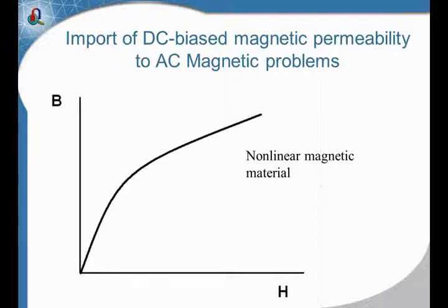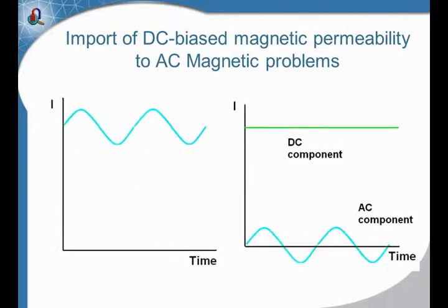In many cases, it is possible to neglect this effect and consider magnetic permeability as a constant, making the problem linear. If the problem is linear, then with time harmonic source currents in complex formulation, it may be considered as a static problem and solved in one iteration without time stepping. This approach is used in QuickField for AC magnetic analysis.